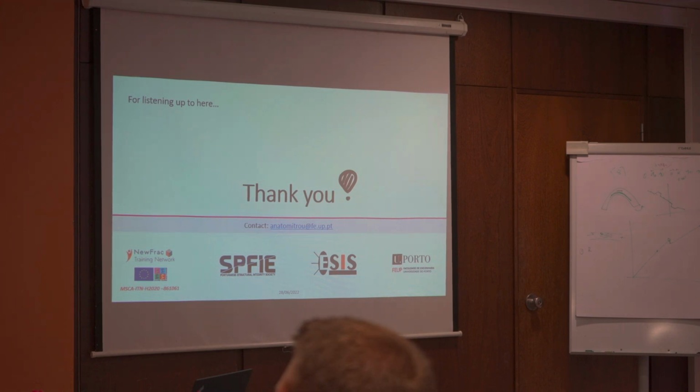Yeah, maybe one rather technical question. I mean, it means you have a layer of elements, right? And every single layer has different local orientations. No, sorry. That wasn't clear. No, that was okay. So I have just one plate. If you can imagine, I have a 2D model that I'm running here. Okay. But you can imagine it's just one plate, represented by the equivalent stiffness of the laminate. I see. And then for the orientation, it's just a matter of putting an orientation, a local orientation in Abaqus.